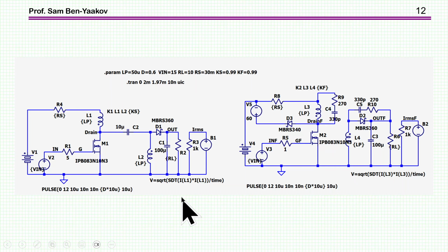So to reduce the oscillation in the Flyback, I've done here what is usually done in actual circuits. First of all, I've added here a clamp so that the voltage will not shoot up too high, and then some snubbers here and here to lower the oscillation.